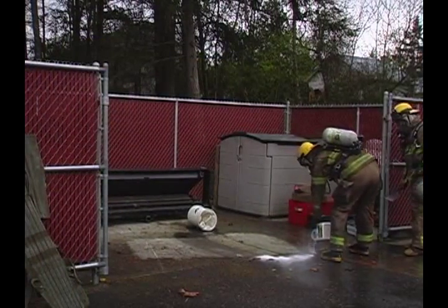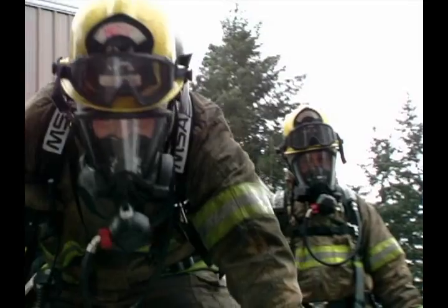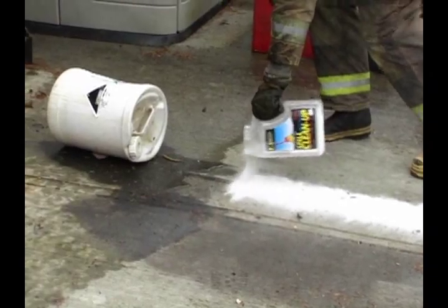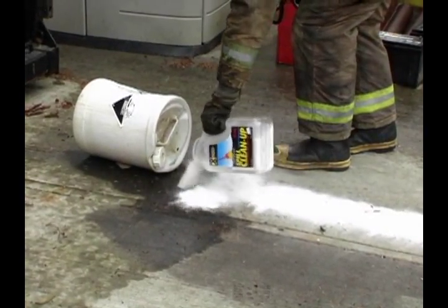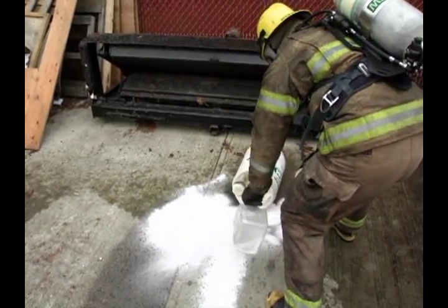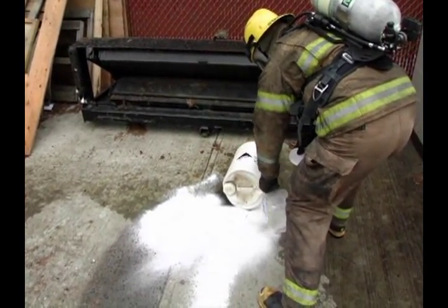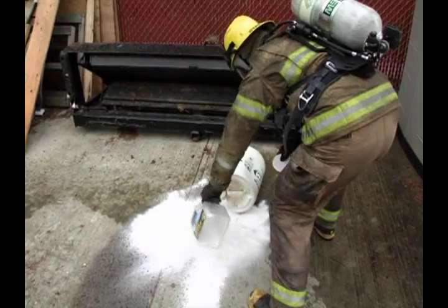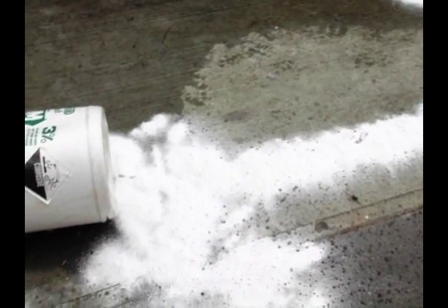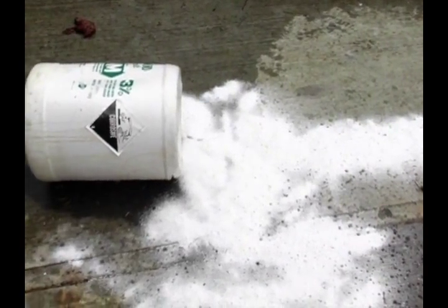At the scene where you have chosen to use absorption, you need to know that the purpose of absorptive materials is to keep liquids from spreading to other areas. Some commonly used absorbents are synthetic fibers, corn husks, clay kitty litter, or ground-up newspaper. An important precaution to remember is that the absorbent will become contaminated and may retain the hazards of the absorbed material.